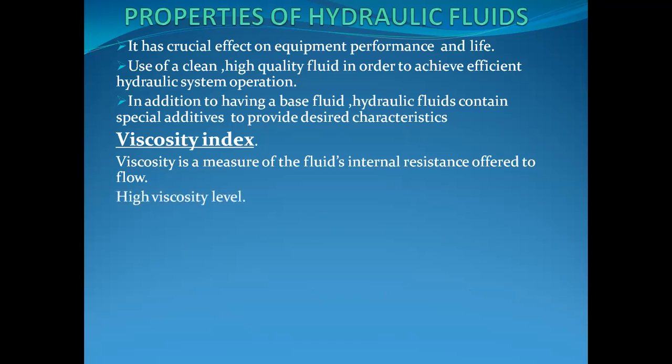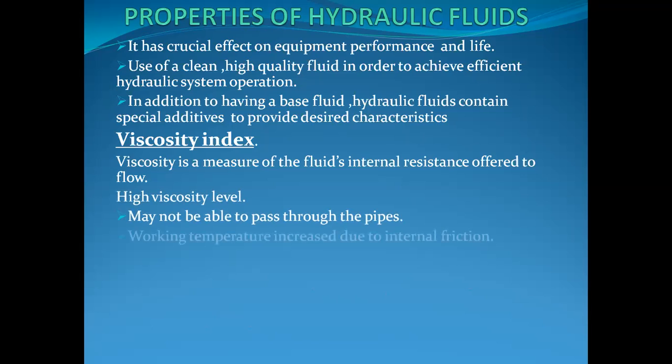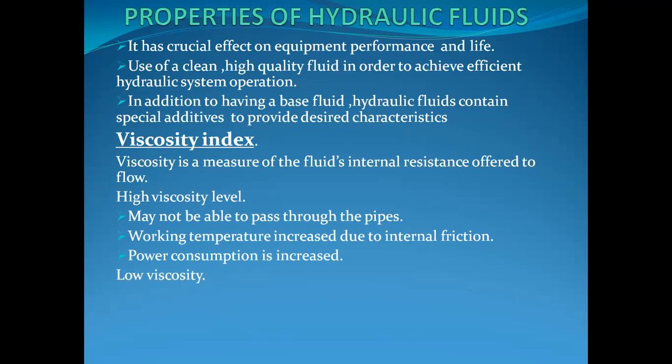Here, we are explaining a high level of viscosity. What happens? The oil may not be able to pass through the pipe. In a hydraulic system, the working temperature is increased due to internal friction because of the slow fluid motion, and power consumption is also increased. Then what happens for low viscosity of fluids in the pipe?